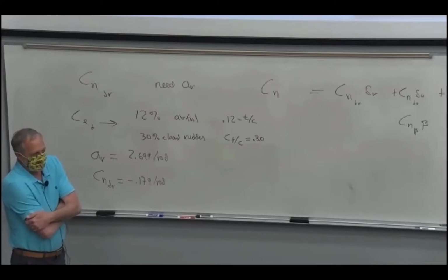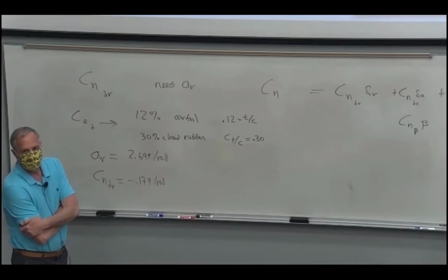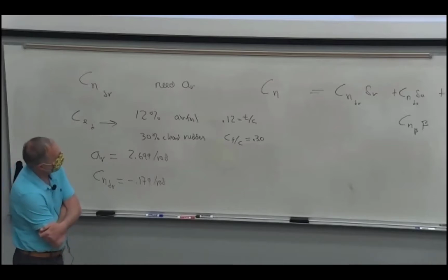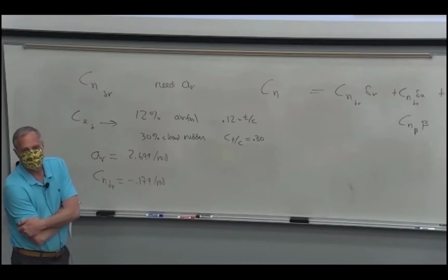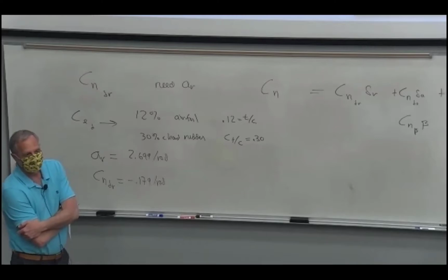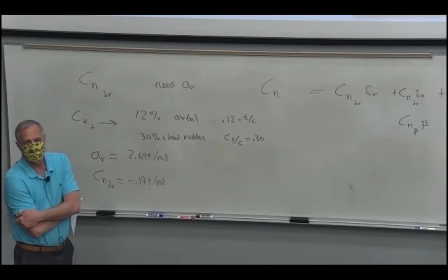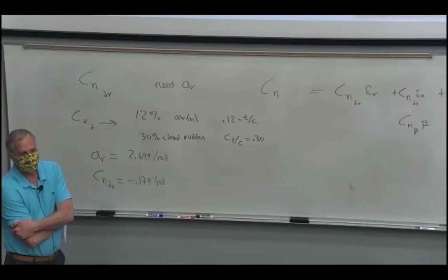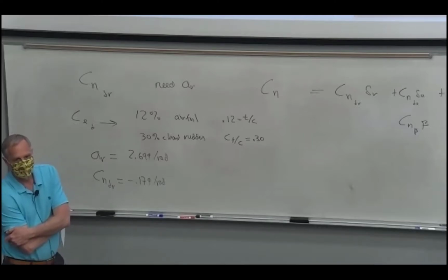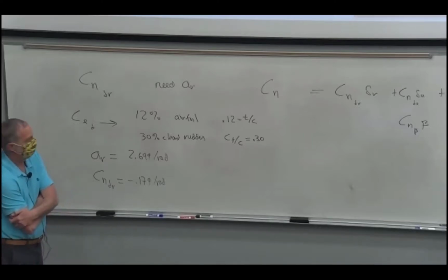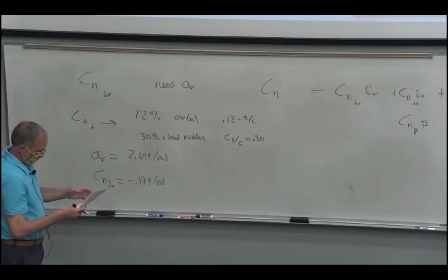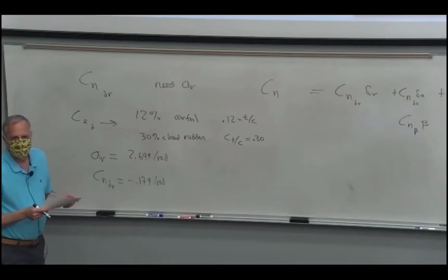And if your rudder happened to be 50% chord, then you'd look up on the bottom axis the 50% line. So this chart works for a lot of different airfoils with flaps. So we could use this for the elevator because it's an airfoil with a flap. But we're doing a rudder right now. Okay, questions on that one? Everybody good?